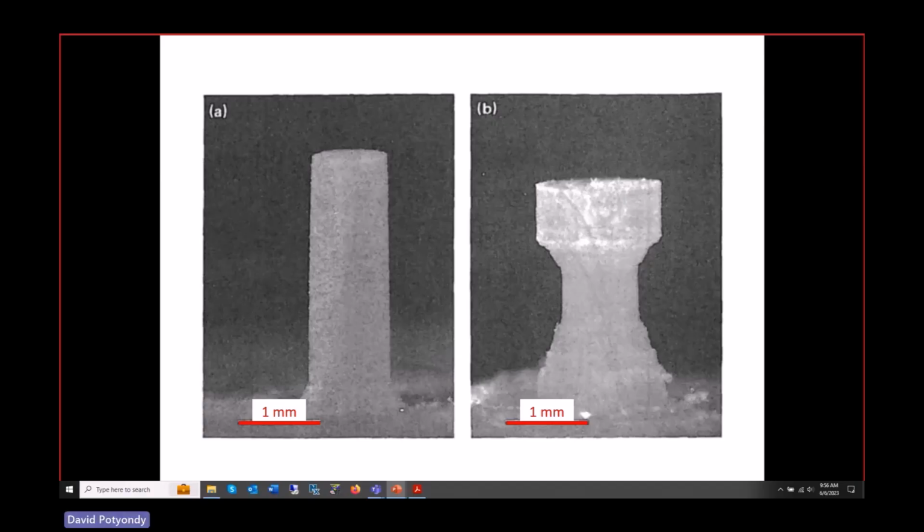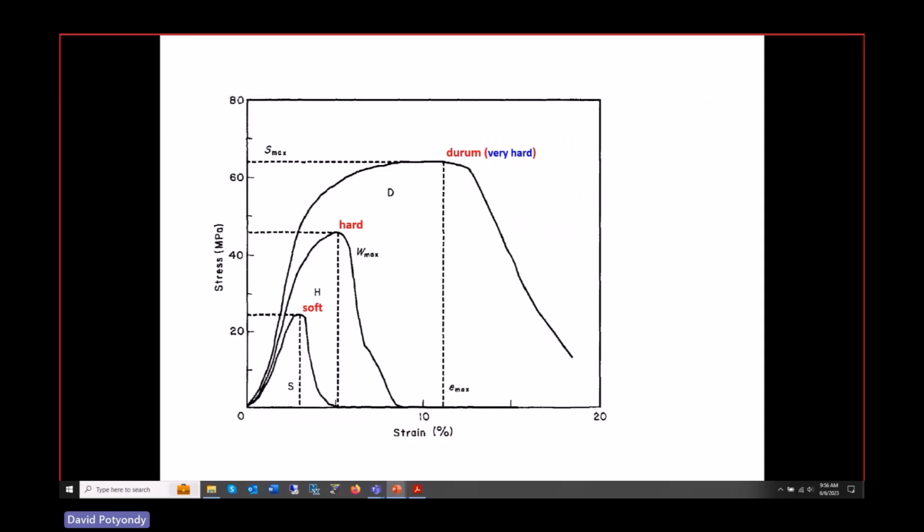Okay, look at this. This is so cool. First of all, here's the stress strain curve. It hardens a little bit, then it goes up and it breaks, and then it breaks, then it breaks. Notice the stresses, 40 MPa. Okay, this is kind of like a rock. This is essentially a relatively brittle material.